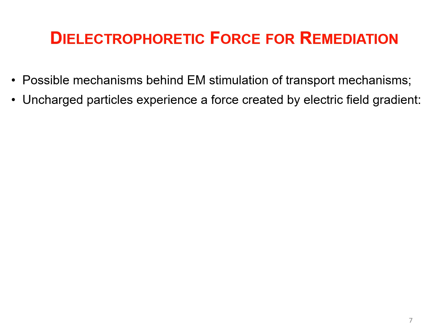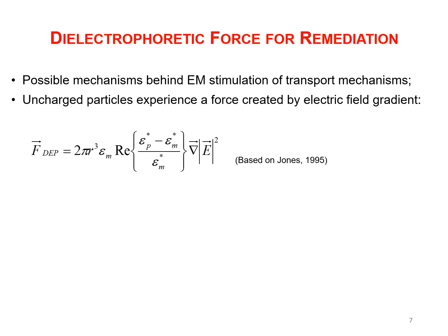In terms of the fundamental theory and what helps us use electromagnetic waves for the purposes we mentioned, the force behind this method is a force called dielectrophoretic force, and the phenomenon is called dielectrophoresis. Dielectrophoretic force is a force that is applied to any particle within a background where there's a contrast in the dielectric permittivity of the two, and it's a function of size of the particles, the properties of the particles and the background, and any gradient in the electric field.